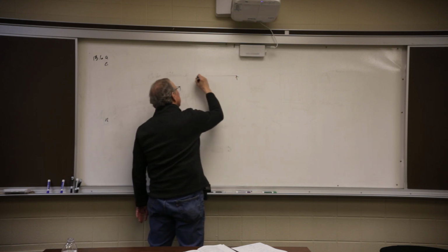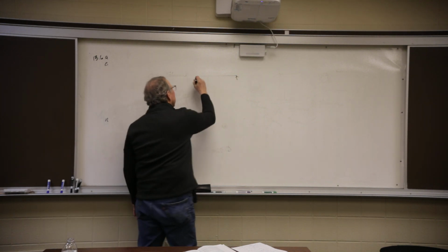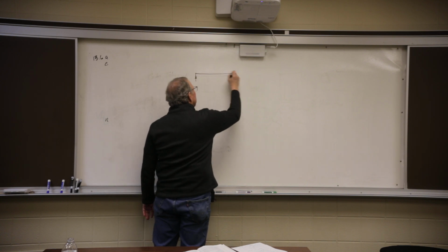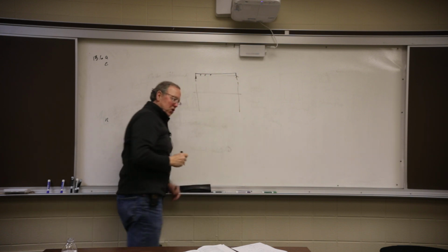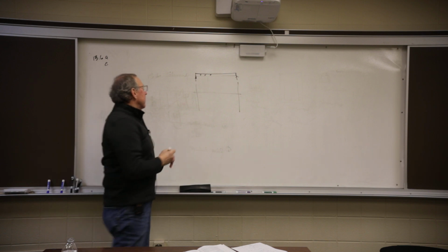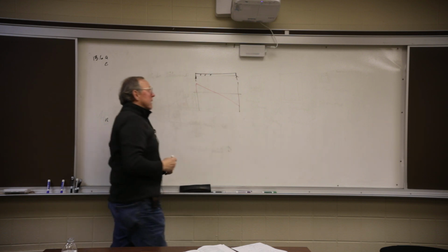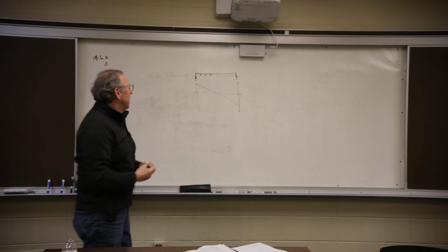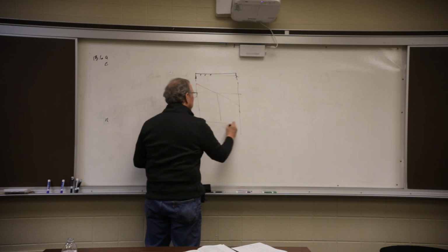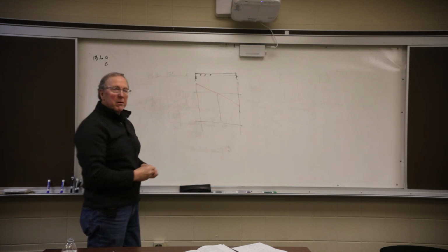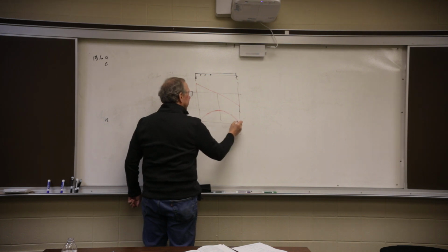And if you go back to page 114 of your text and look up case 2, it'll show you a little picture of a beam with a uniform load. And underneath that picture, it has two pictures. One, which is the shear diagram, and that looks like this. And the other is the moment diagram. And the moment diagram, of course, is centered right underneath the shear diagram. And the moment diagram takes a parabolic shape, and it looks like this. So that's the shear and the moment.